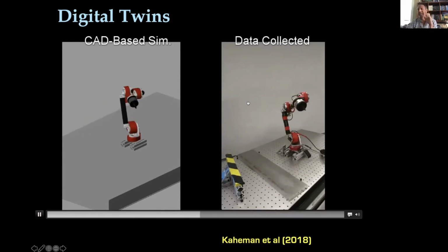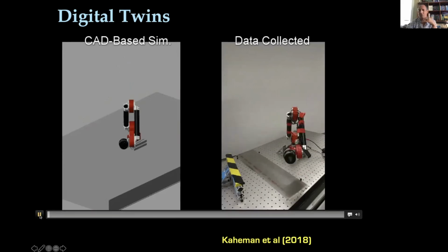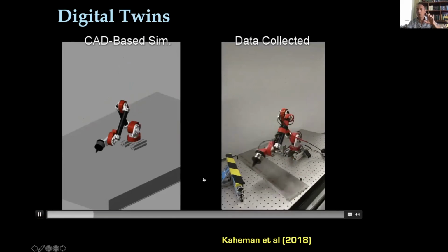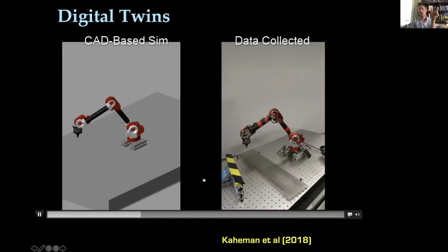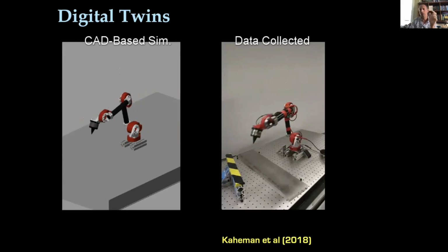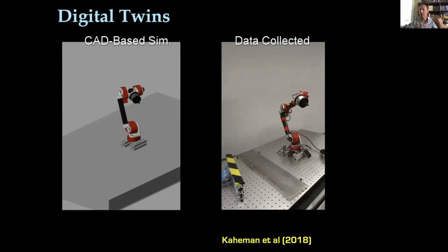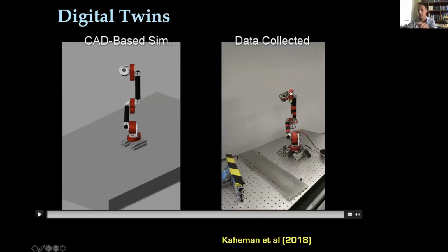this model is not accurate enough to capture this real robot arm because, in fact, there are frictional forces; each joint has a little bit of stick to it. So what you could do is say, well, I know my governing equations, I know parts of it to be true. I can use the same regression framework that I just showed you to build a library of the potential missing physics terms, do the regression, and now learn in an adaptive way what the difference between these two models is.